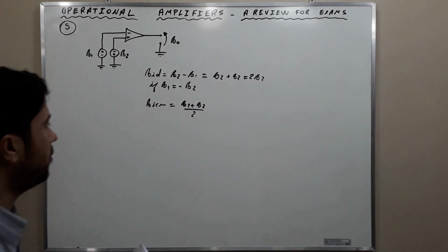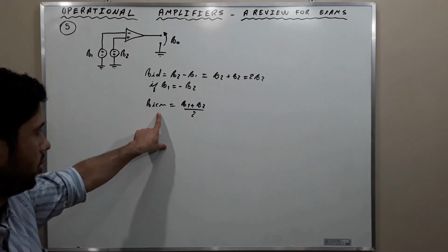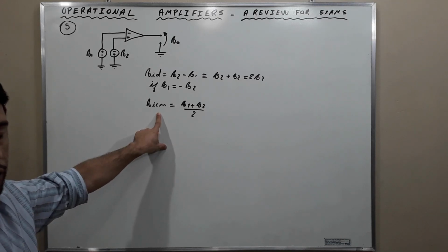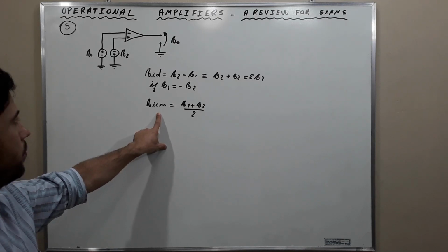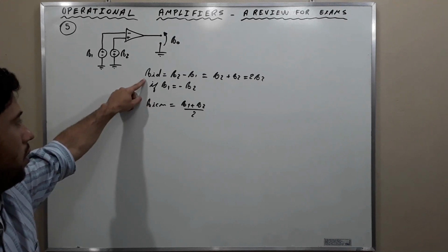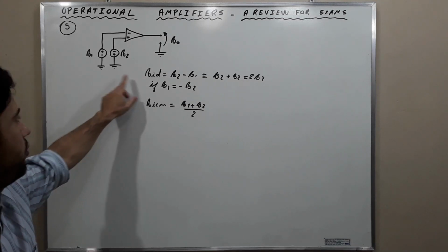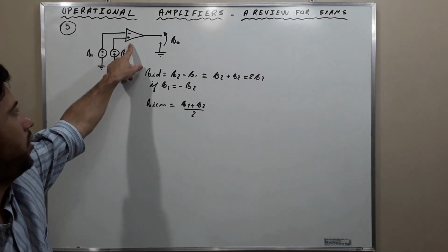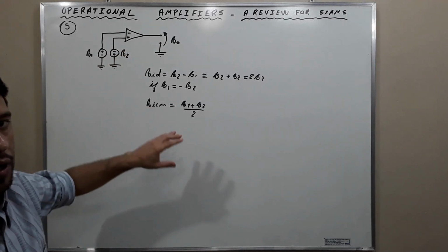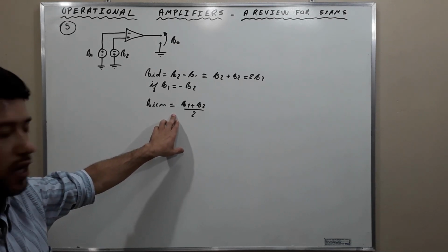This is the definition of the common mode voltage, which is also amplified by real, in other words, non-ideal op amps. Ideally, operational amplifiers only amplify the difference between the signals applied at the input terminals, but real amplifiers also have common mode voltage amplification, okay?